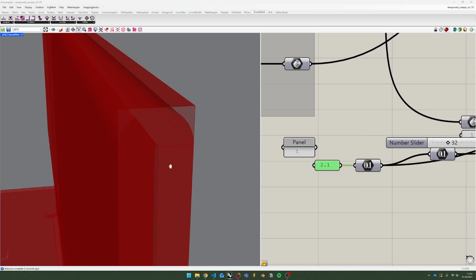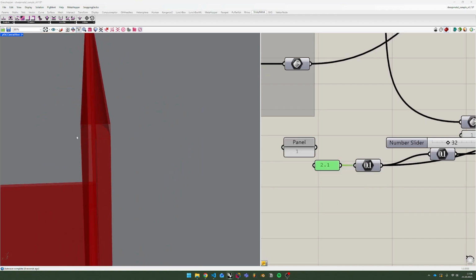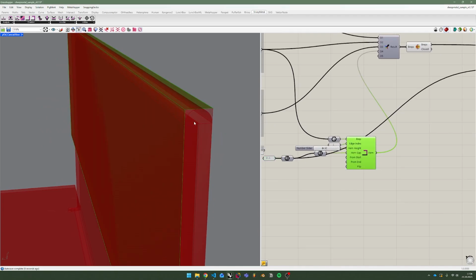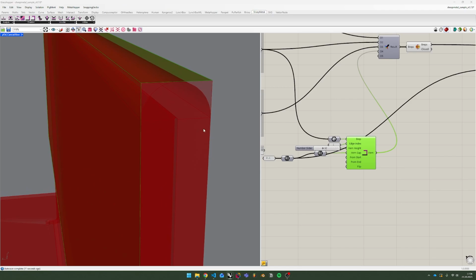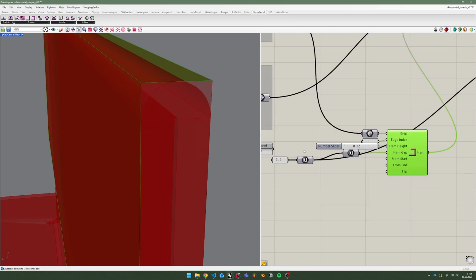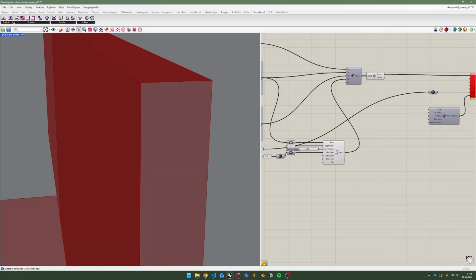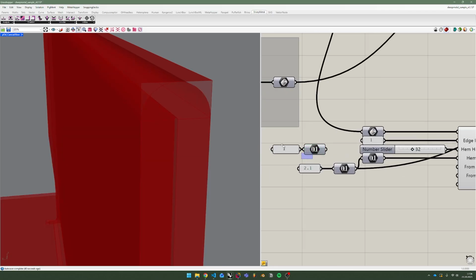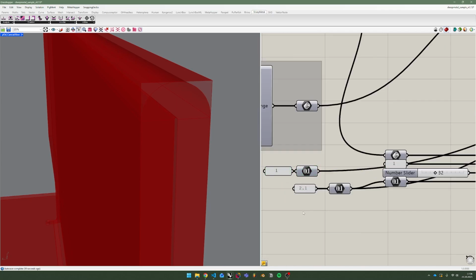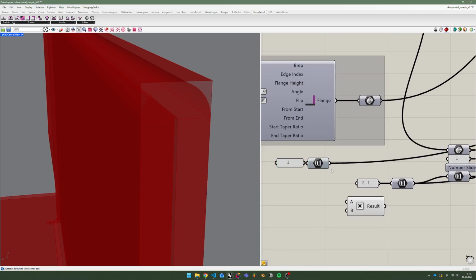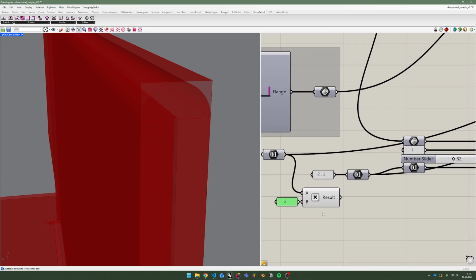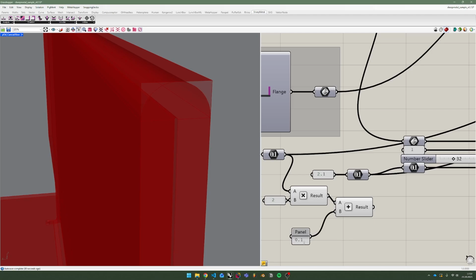As you can see now it's working. So that's something to consider while designing the sheet, to be careful that it doesn't self-intersect while offsetting. So sometimes you need just the hem gap, but sometimes you need 2 times the sheet thickness plus the hem gap. So let's do some little calculations to automate this process a bit. So if we change the thickness of the sheet, it will not directly fail again.